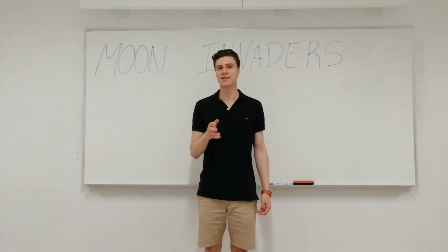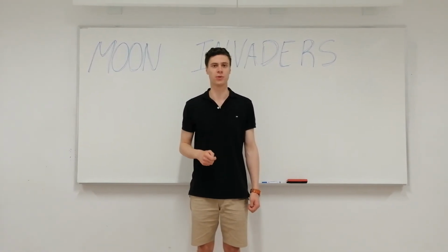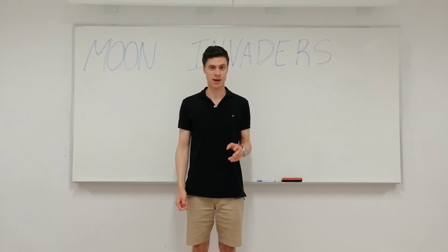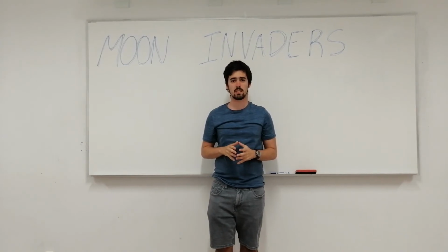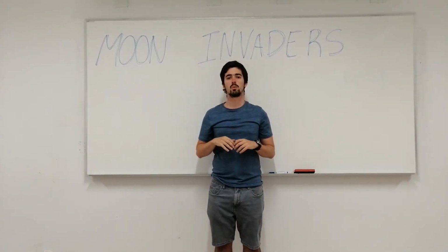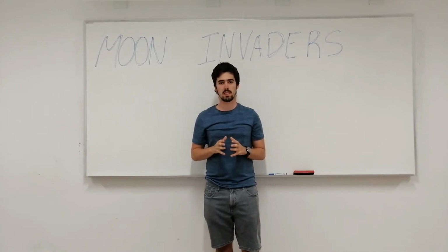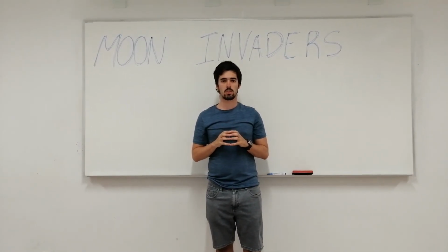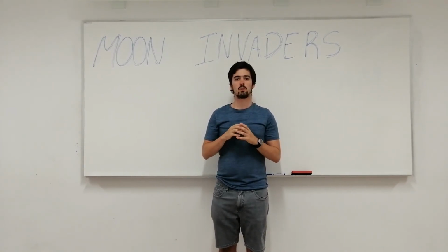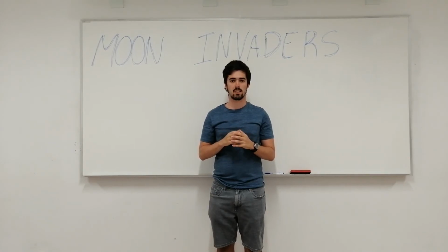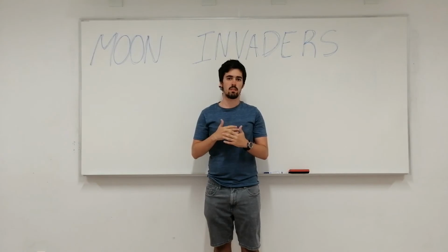The final solution is a 6U CubeSat of 14 kilograms that performs 2 flybys over the Moon's south pole. The payload consists of a camera and 2 spectrometers. It has 72 solar cells that provide power to the entire mission. The attitude and orbit control subsystem is composed of 3 main reaction wheels plus 1 to ensure that the system remains functional if one of the main reaction wheels fails.